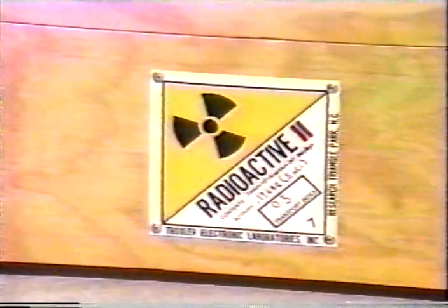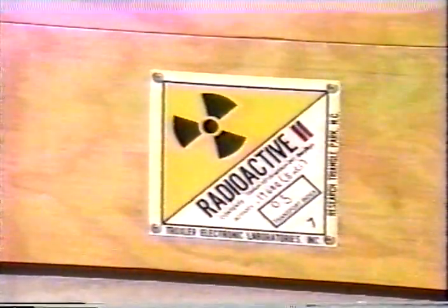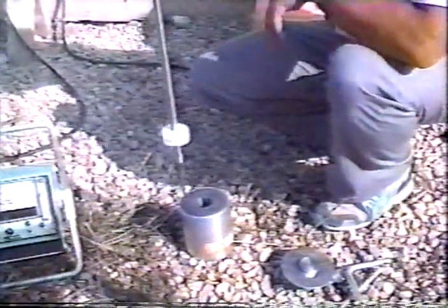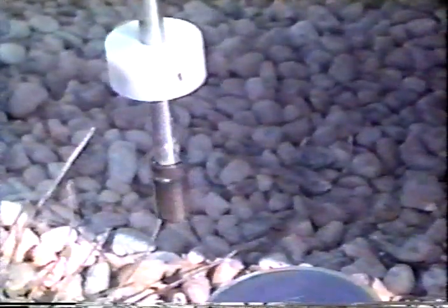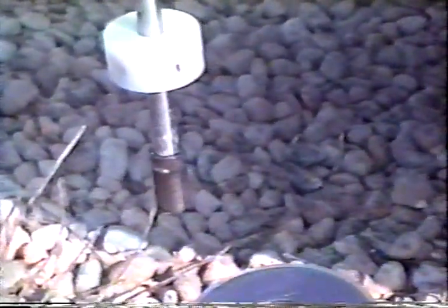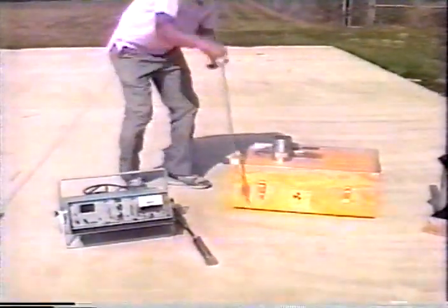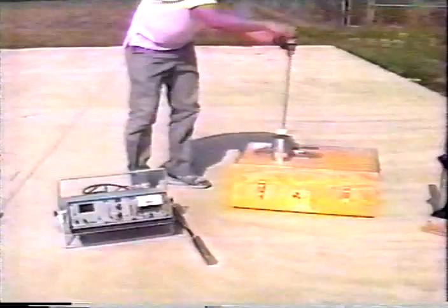The most important thing to keep in mind when working with nuclear gauges is safety. Gamma radiation is potentially harmful. Like X-rays, it can pass through solid materials. Only trained and certified personnel should operate any nuclear gauge. The user's manual contains additional safety information.